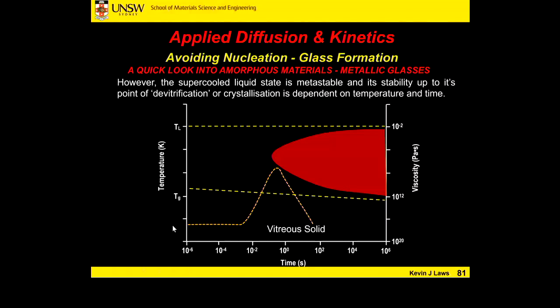What we have to do, at room temperature, we're below this glass transition temperature, yeah? To form the material, we have to then heat up. And we're on a ticking time bomb, so to speak, before we hit this crystallization curve when we're above TG. So we have to heat the material up, get above the glass transition temperature where it relaxes and we can form it like chewing gum, and then we have to quickly cool back down before we hit the nose of that crystallization curve. So now we have our vitreous solid again, but it's now been shaped into something useful.